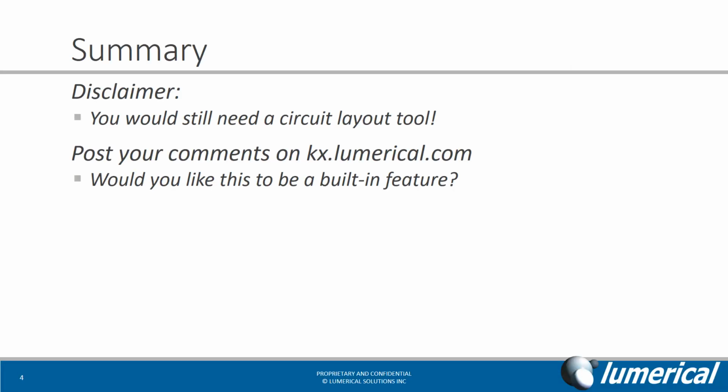Okay, that's the quick demo. I hope you will find this feature useful for your design work. Just to clarify, this feature is not intended to replace the circuit layout tools. Rather, the purpose is to help you export the geometry of a component that you already set up in FDTD solutions, mode solutions, or device into a GDS2 file, which can then be added to your circuit layout. You would still need to do the routing in the layout tool.